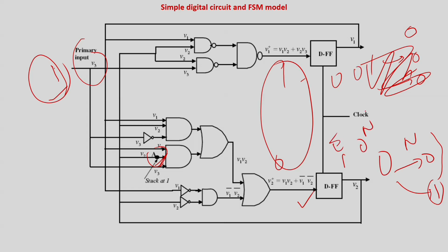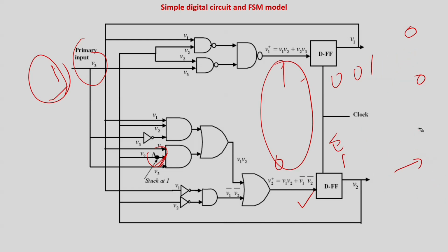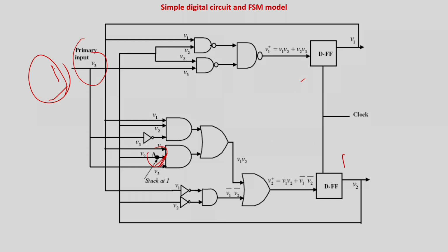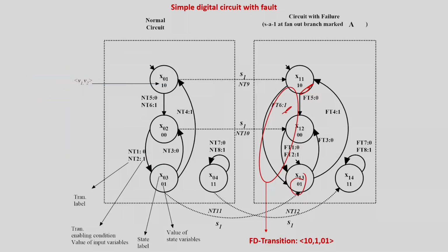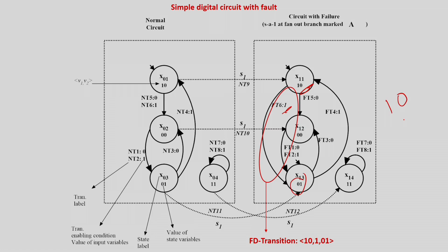So this one you can easily find out by your normal ATPG mechanism also. But in this paper, the theory I am discussing is on online testing design in finite state machines. So they handle it in a different way, and then they remove the complexity. But you can take it from me, the same test vector can also be found by ATPG or by n number of different techniques. Like normally we do by the scan chain method, or by what we call the time frame expansion method. Any method you can use. But for the time being, we can find that present state 1 0, input 1, next state 0 is the fault detecting line. So that is what is actually going to detect the error.